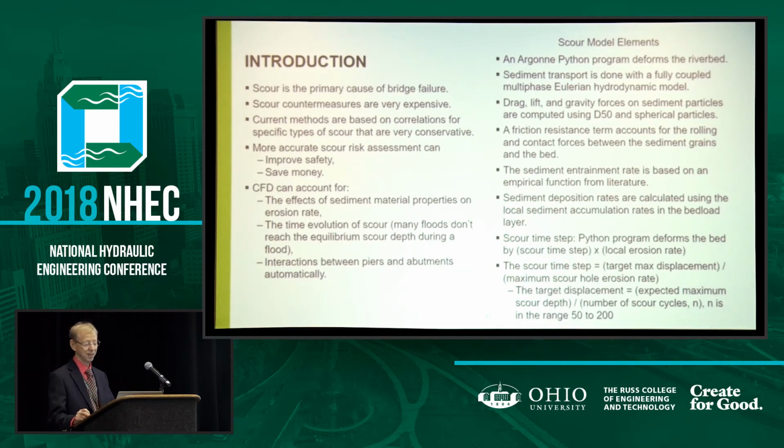We have two basic computations we go through. We compute the fluid flow, and we compute the entrainment rate, and then we inject the sediment as source terms in the differential equations, and then you compute that motion downstream and where it settles out. And that kind of reaches, for a particular bed topology, something close to steady state.